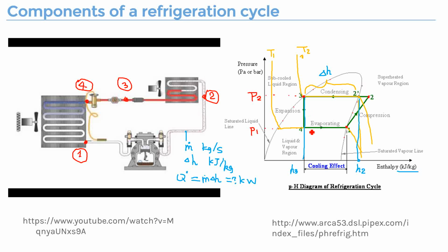So from point 3 to 4, you can see the pressure just changed from P2 to a pressure we don't specify, but it must follow this line of constant H. So there is no energy loss, and we must draw a vertical line. When you draw this vertical line, H4 equals H3, and also a horizontal line from point 1, because we say there is only phase change, no temperature change, so you can find point 4. So that's how, starting from point 1, you get 2, 3, and 4.